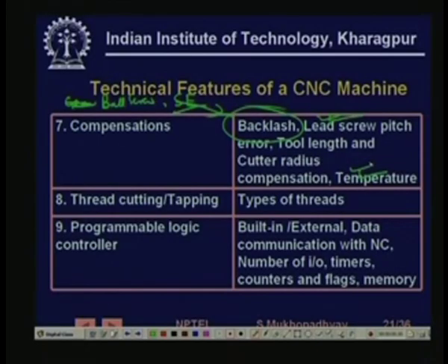But for that, the tool has to be moved with certain offsets. Because the tool will get worn, these offsets are to be regularly measured, and then the proper compensation should be given. Similarly, for very high temperature, firstly product quality can be affected, and secondly sometimes dimensions can also be affected.